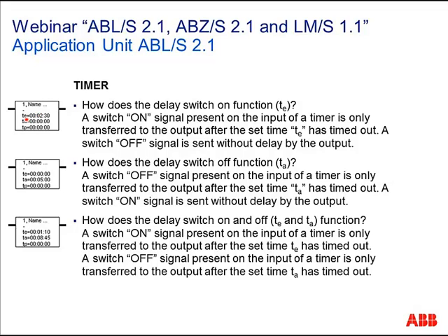TE means the on delay. So it receives on the input the value 1, and then our on delay time starts. After, for example, 2.5 minutes, it sends the value 1 to KNX and switches maybe your fan or your blower on, delayed. Our off signal will be transmitted immediately to the output. And here is our off delay time, for example 5 minutes, the same principle.